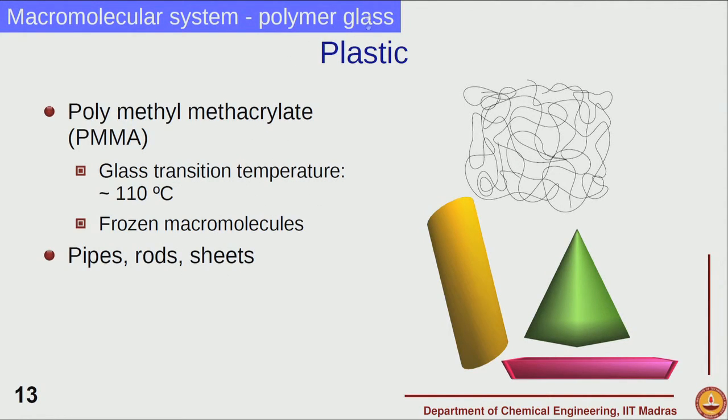These materials are largely solid like, but depending on the time scale of interest they have several viscoelastic features. Given that the molecular arrangements and the basic mechanisms present are similar in the rubbery and melt states, the only thing is the time scales are very different. Later in the course we will define something called a relaxation time, and we will see that one characteristic of the glass transition is that the relaxation times are extremely large, while in the rubbery and melt states the relaxation times are lower. However, one can look at these transitions from melt to rubbery state and rubbery to glassy state in terms of these relaxation times by doing rheological analysis.